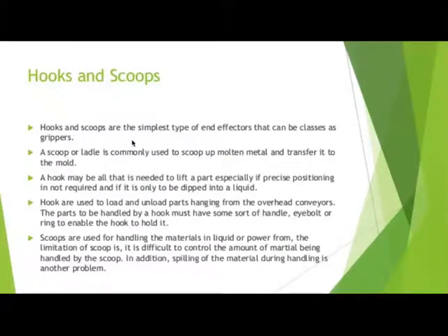And now there are hooks and scoops. Hooks and scoops are the simplest types of end effectors that can be classed as grippers. The scoop or ladle is commonly used to scoop up molten metal and transfer it to the mold. The hook may be all that is needed to lift the part, especially if precise positioning is not required, and if it is only to be dipped into a liquid.